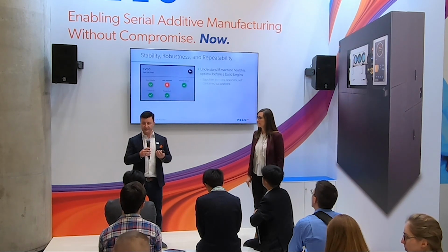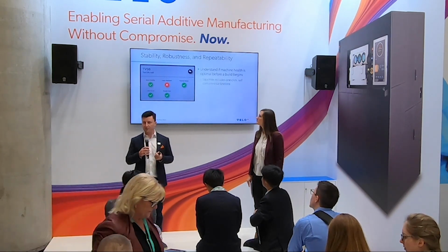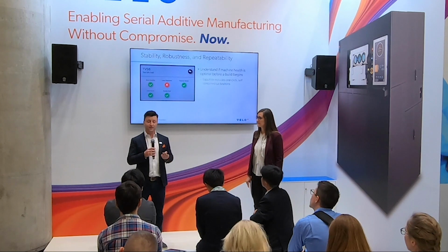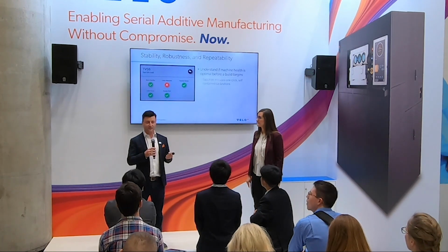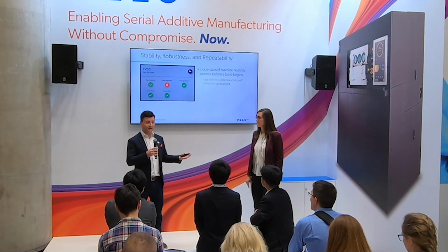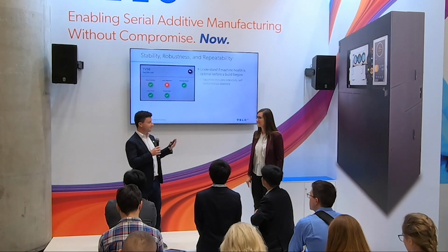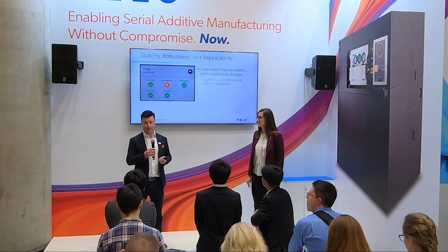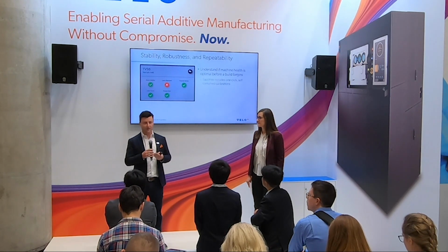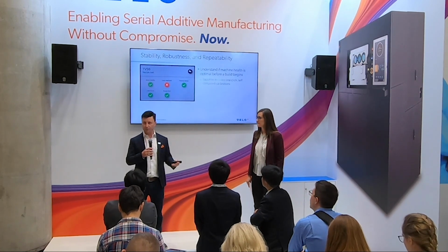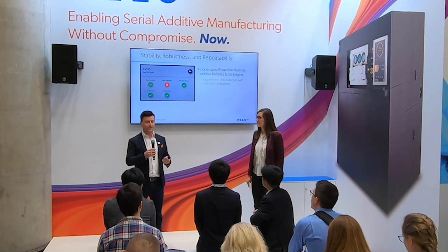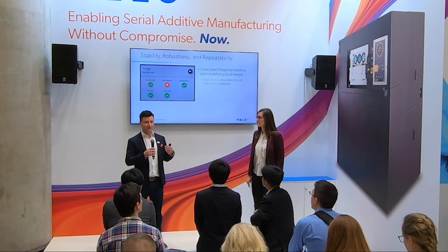The reason I say that is that with many metal laser powder bed systems, when you start a print, you don't necessarily know the state of the machine. You have a complicated optical system, and it's time-consuming to calibrate in general. A lot of times this requires a field service engineer to come and do hours, if not days of work, and this is something that's performed on a PM interval.